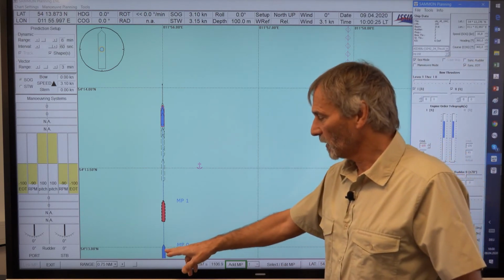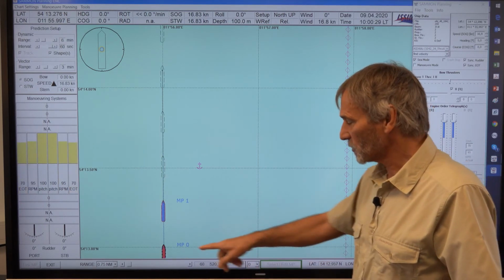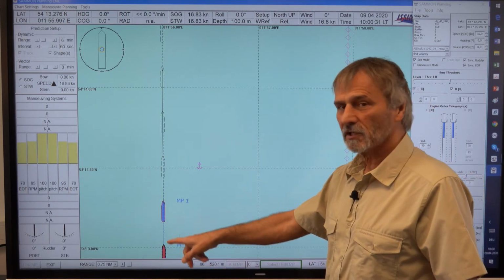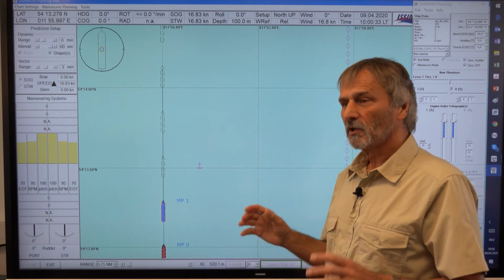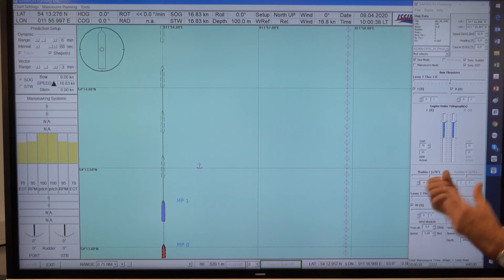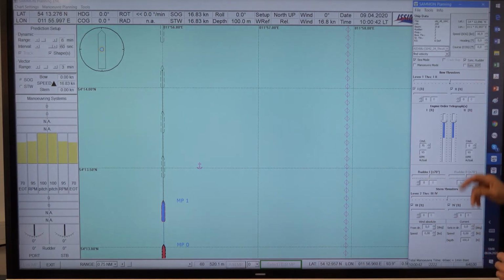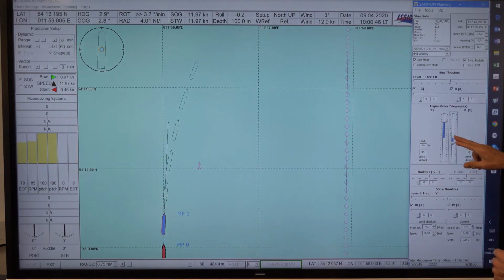And so in this position number 1, I go back to the initial position here, and the 60 knots which I have here, we don't do with 70% of both engine ahead, but instead I desynchronize the engines, and so I can pull one engine back maybe to only minus 10%.